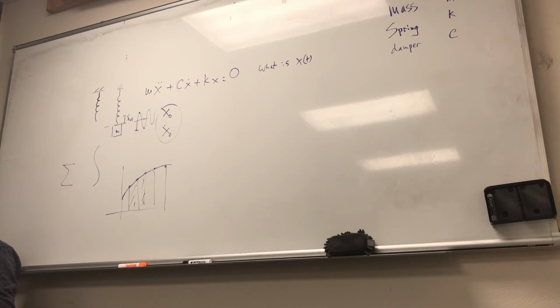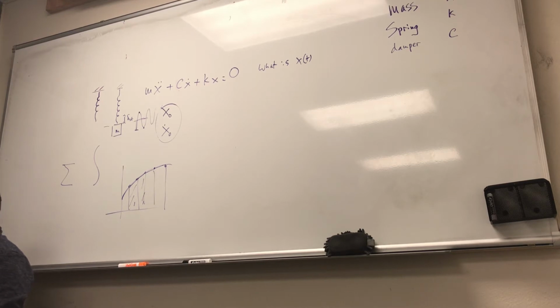Now, one thing you need to know though, if the frequency of the external force, in other words, the way I'm forcing it like this, coincides with one of the natural frequencies of the system, a condition known as resonance occurs and the system undergoes dangerously large oscillations. Now, why does it say here coincides with one of the natural frequencies of the system?